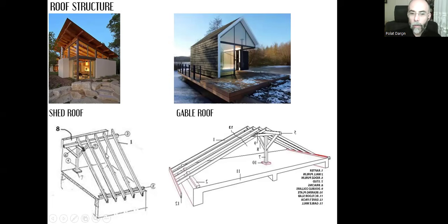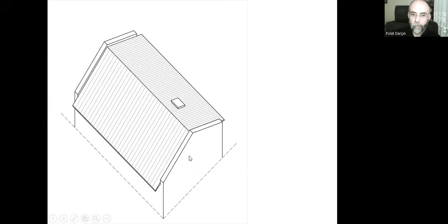There is this rafter system, the same thing with the wall purlin and the ridge purlin, and the same system of rafters is mirrored towards the other side. There is this other eave here, one eave and the second eave. We are placing the second wall purlin, the same ridge purlin here, and the same type of studs and the bracings and the collars and everything.